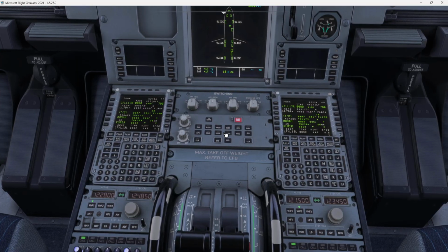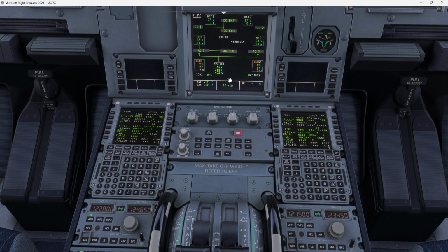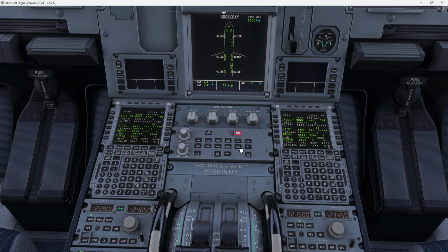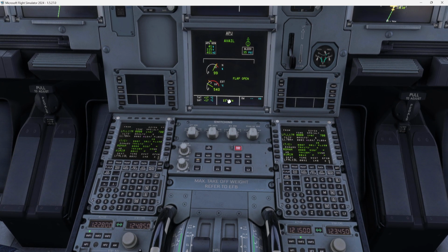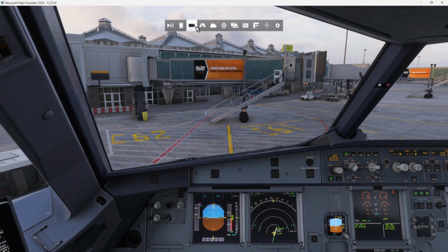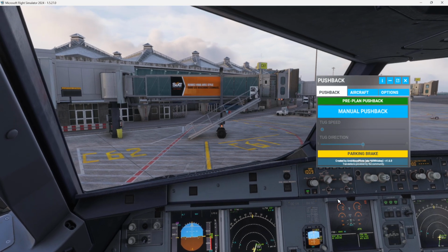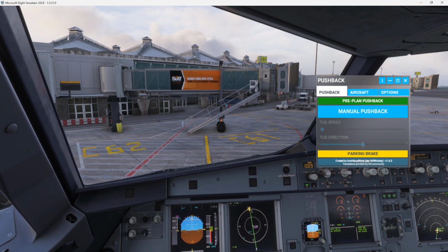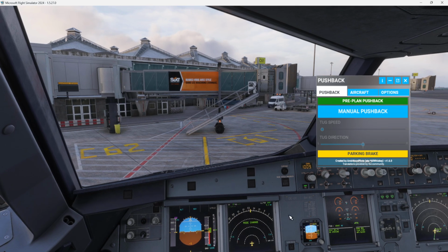Okay, let's go here to see the electrical page. We have the APU generator supplying AC1, AC2, perfect. Let's go to APU. We have the flap available, 41%, 115, 400. That looks perfect, and the bleed. That's nice. Perfect, guys. Let's start the pushback and notify the frequency. We are pushing back in this scenario facing east, no, facing north still. Yes.